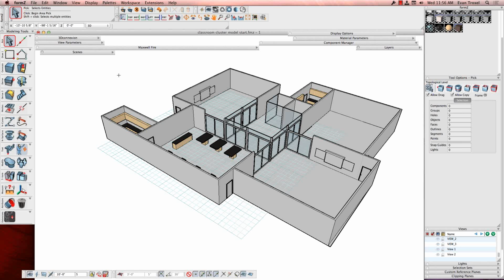Chuck wants to know, what is the extension at the bottom of the modeling tools? The extension at the, oh, okay, this little guy. This is because I have the Maxwell Render Suite plugin installed. So extensions in this case is Maxwell specific stuff. So I can use Maxwell C, volumetric objects. I can place some MXS files, which are Maxwell scene objects.